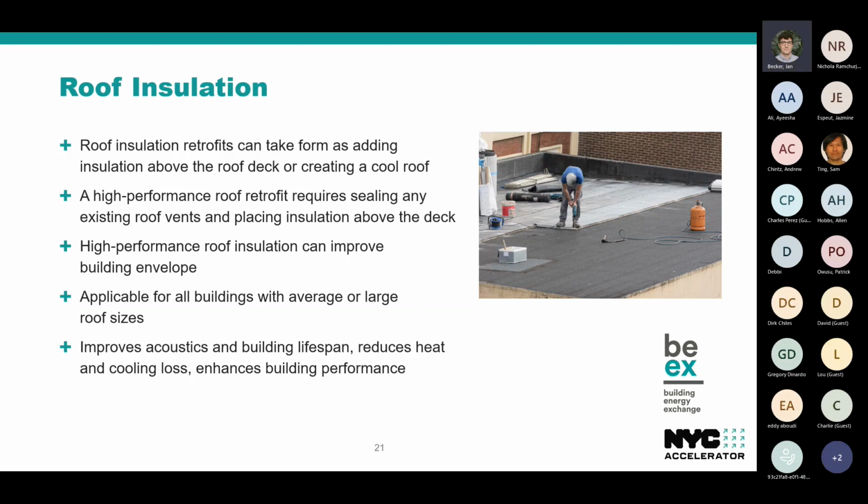And a high performance roof retrofit requires sealing roof vents and placing insulation above the deck. It requires a correct installation of the vapor barrier, so that water vapor does not condense within the assembly. Basically these can be complicated projects. They can be pricey. So if you're looking at a potential roof replacement and you want some technical assistance, because it's a lot to think about, please get in touch, and we'd be happy to help you. So that's it for me.